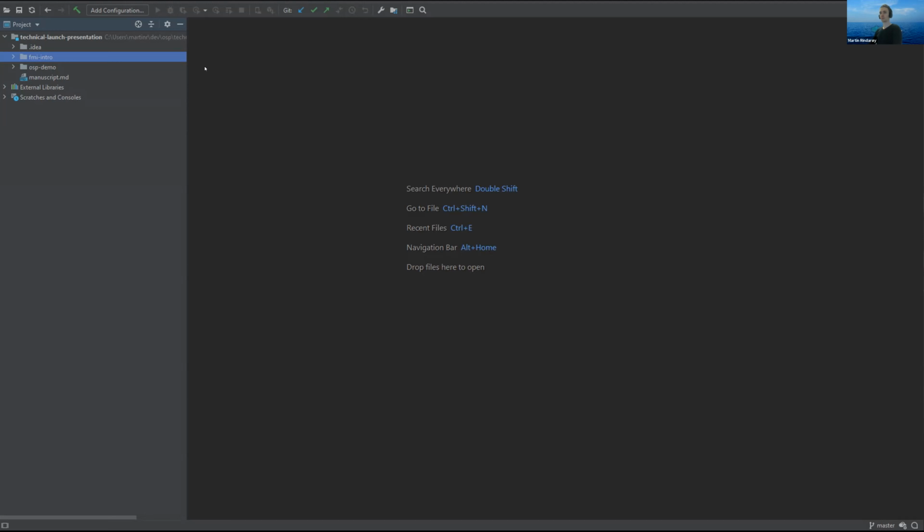Then I will go on and demonstrate how to make OSP model description XML files and OSP system structure XML files. And finally, I will run some examples using the command line interface tool with the OSP validator to validate some OSP system structure XML files and some valid ones and a couple of examples with some validation errors.